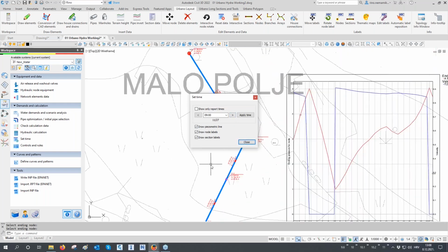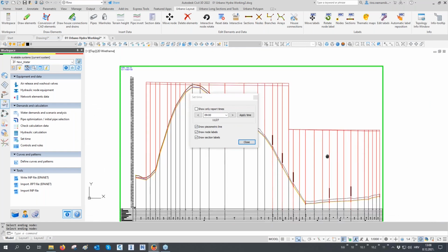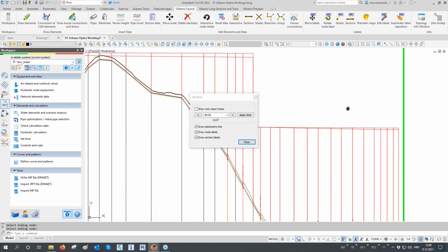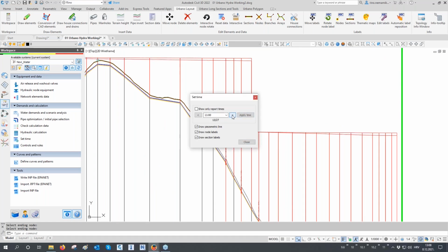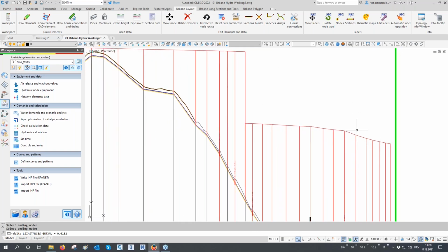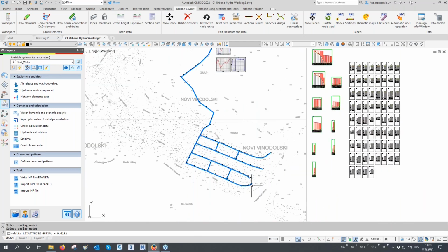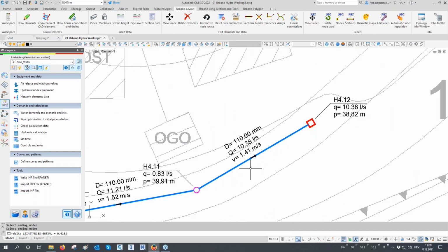and you have the flows. And also if we go to our profile, we can check the dynamic piezometric lines. So check how they are dynamic, they are moving. And for example, when you come to some part of the day that you would like to save and apply, you can apply it. And now these results are applied. So here you have the permanent piezometric lines, you have the permanent labels now applied, and they are now showing our peak flow.